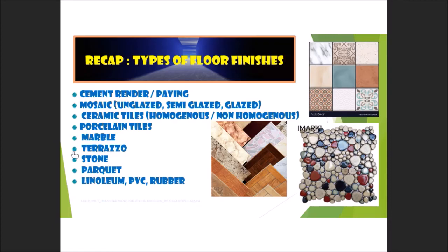Okay, this slide actually show the recap on the various type of the floor finishes. We have semi-render, mosaic, ceramic tiles, porcelain, and so on. And I also would like everyone to take note that in terms of the material, you really need to know, or maybe you have to search some information if you cannot remember. For example, mosaic is having similar detail as the ceramic tiles, but what shows the difference is normally according to the size.